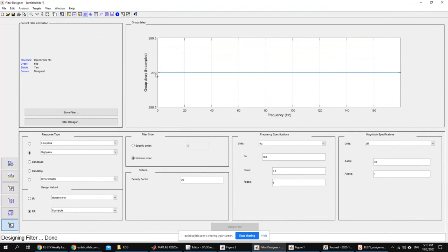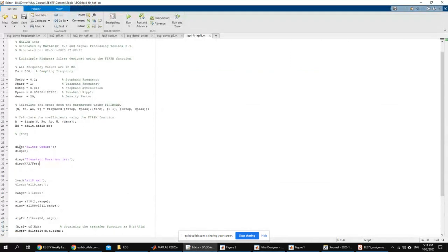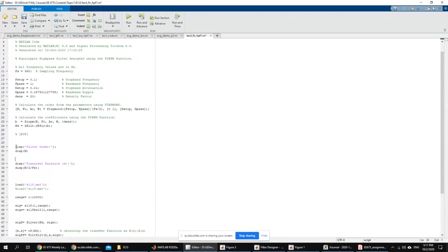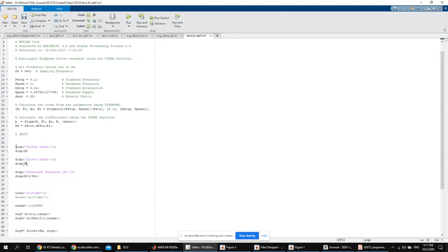Is it related to the order? As you said before, in the FIR filter, it is related, and it is exactly equal to basically the order over 2. So for an FIR filter like this, I can say that the filter group delay is equal to N over 2.